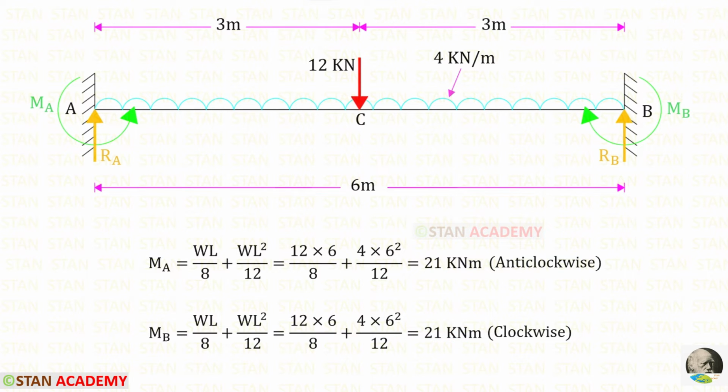In this beam, we have symmetrical loading. That is why for both of the moments, we have got the same value, but MA will be acting in the anti-clockwise direction and MB will be acting in the clockwise direction.